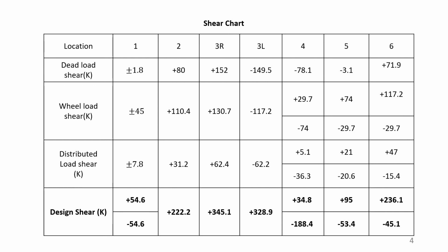We have just added these values, plus with plus, and they come up as added values. In shear we have only one form of shear, either positive or negative, whichever is the maximum, and we will design the sections, the shear stirrups or shear reinforcement, for the maximum numerical values.